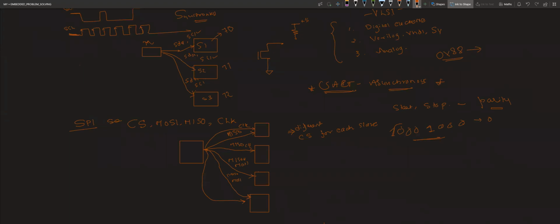So far we were using the Arduino tool, through INO files we were flashing. Internally, we discussed that there is a TCP/IP stack inbuilt in that ESP processor. Now we have to reflash that ESP with the Python-based firmware, MicroPython firmware. So first we need to connect that NodeMCU to our laptop.